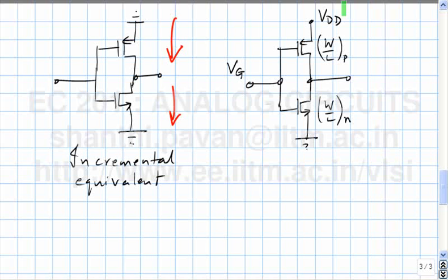So it seems quite nice that you can stack them on top of each other, and they should be happy as long as the proper bias is applied to the gates. The question now is, what is the gate voltage I must apply such that both these transistors will be in saturation and the drain currents will be the same?